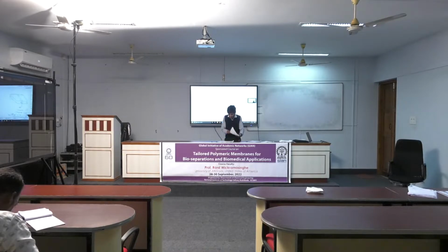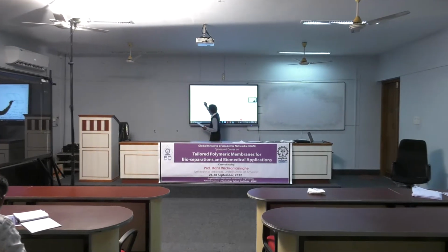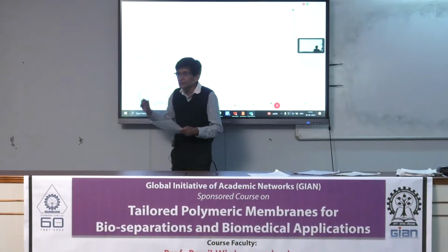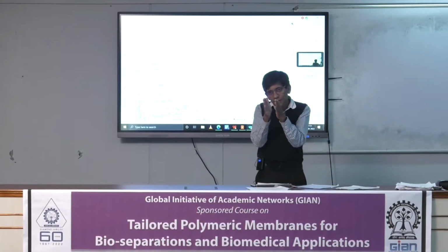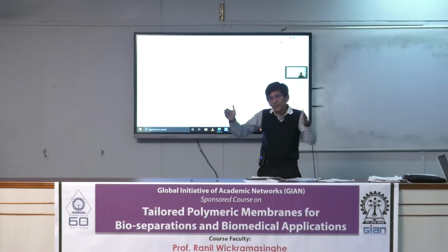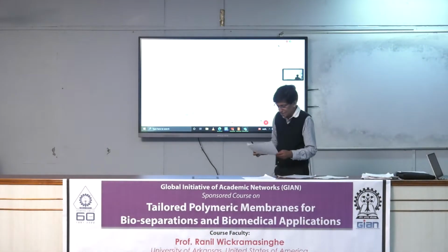And again, I'm going through the mathematical version. If you're not an engineering student, it will be more difficult, but you can at least see qualitatively what's happening. So qualitatively, we're trying to work out the rate of transfer of this urea from the blood into the dialysate. So what we typically do in engineering is we consider a mass balance on a small volume. What we're doing basically is we're looking at what happens in this small volume, and then we're going to average for the whole membrane, okay? And that's where this integration comes in.